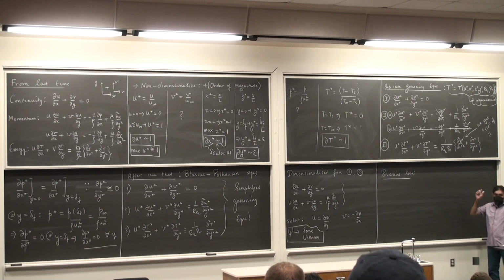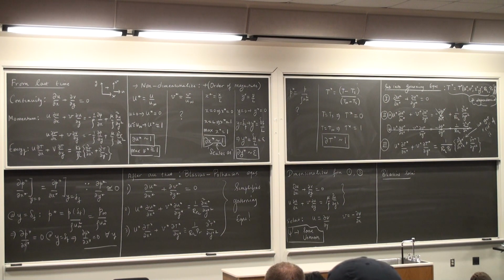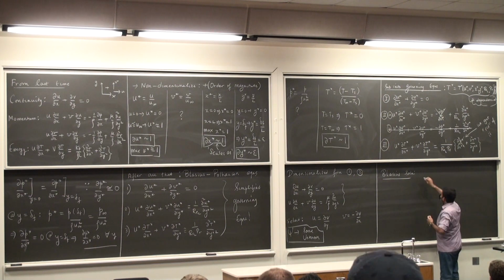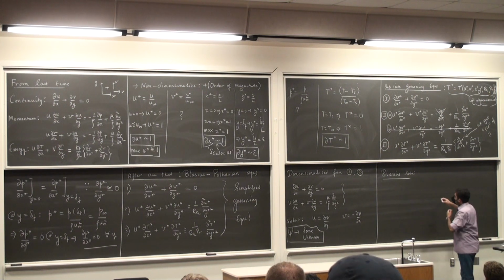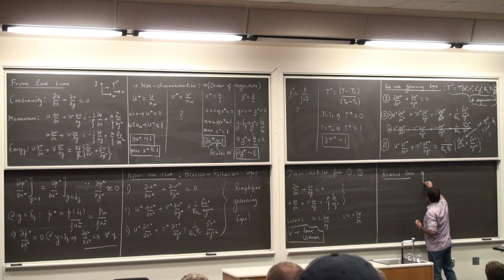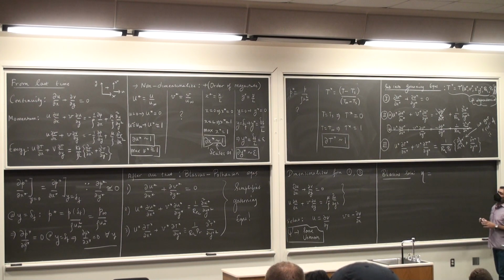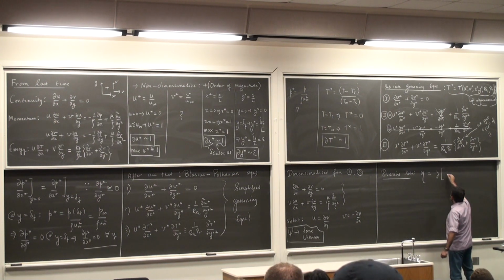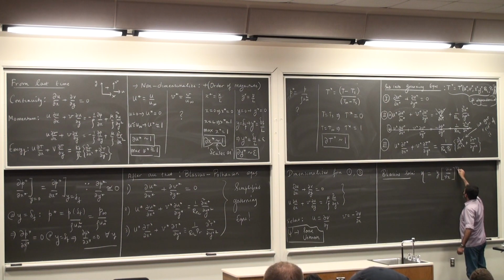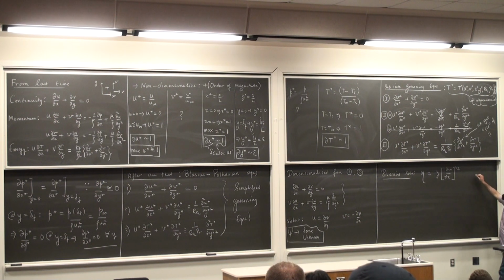By cleverly, meaning cleverly for us by looking at the book, for Blasius it was a lot of intellectual sweat. So when we look at it, here is the final form. At least for me, it is just looking at the book. We have actually obtained this. If you take a higher level fluid mechanics course, they'll derive it. So you select eta, some variable eta. Okay, it is y times u infinity by nu times x to the power 1 by 2. Nu meaning the kinematic viscosity,